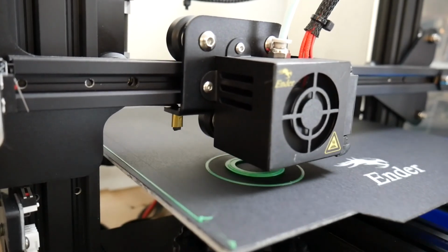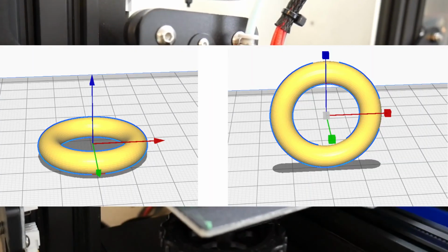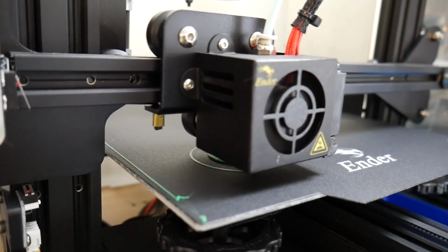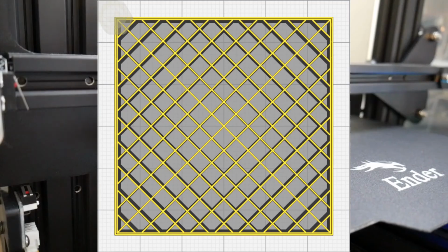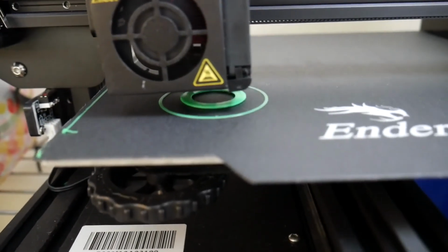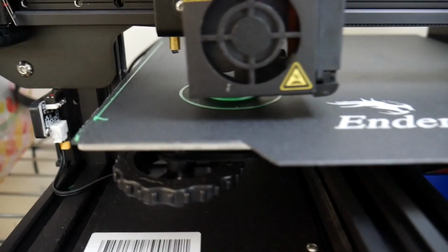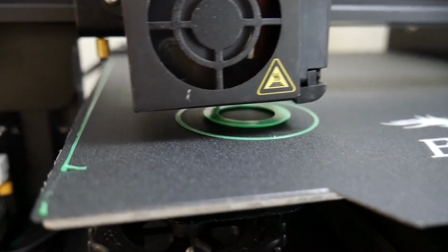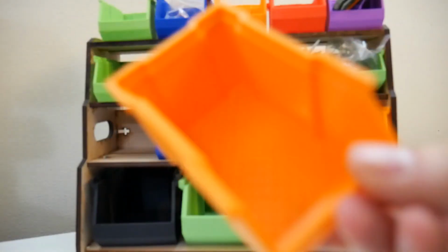In summary, we talked first about the basics: orientation, overhang, scale, and supports. Then we went into more advanced topics like print quality, infill, and build plate adhesion. This video condensed a lot of topics that might take time to grasp, but don't be afraid to revisit a topic again, and above all, experiment with the slicer software. Remember, design your model for the manufacturing process.